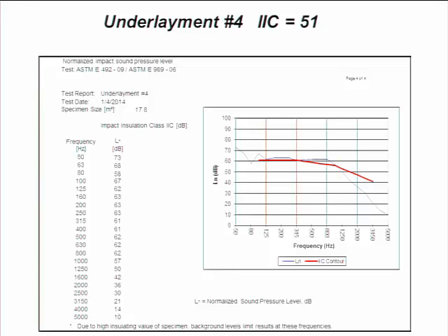What it does at each frequency says a lot, and it depends on what sound is being produced through that floor. What sound does it stop, even though it's the same rating? So basically, from a lab's point of view, to close, IIC and STC ratings are only good for flooring on a specific floor assembly. For this reason, many different assemblies are needed in the laboratory. Remember that slide with all the stacks of assemblies. Although IIC and STC ratings are the best system to compare products on like assemblies, sometimes they do not tell the whole story.